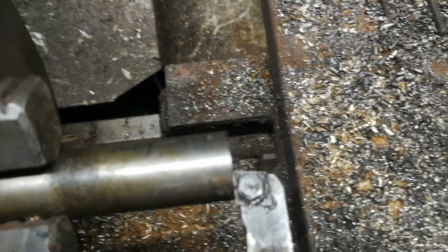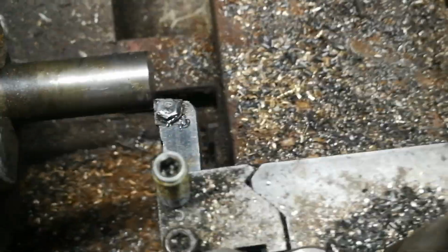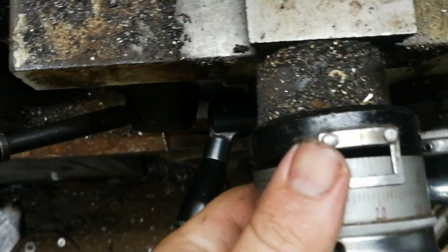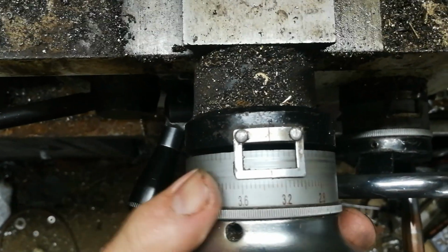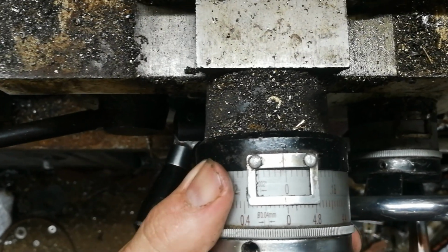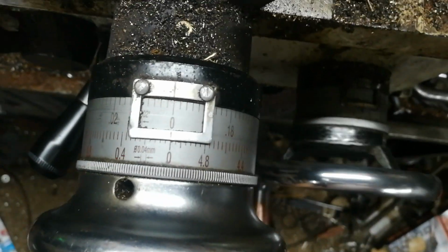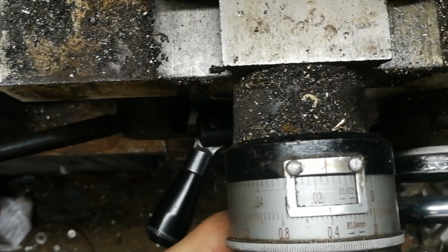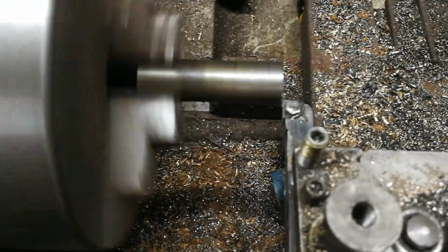Ferrous metals, i.e. steel, and materials such as plastic and aluminium should be turned using a water-soluble coolant. If a coolant pump is not available, a washing up liquid bottle works well. You can also use a spray bottle or even something like WD-40, especially on aluminium, will work okay. Plain motor oil can be used, but this doesn't work as well.